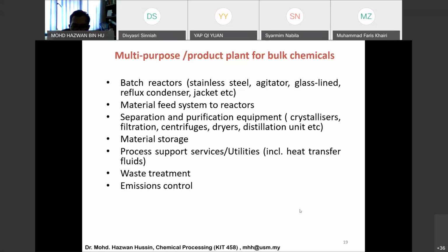So in industry, for your information, if you want to do heating, we are not going to use a Bunsen burner. We are not going to use a heating mantle, because the temperature required in a process can sometimes be too extreme. Then these two things, like a burner, will not be useful. And of course, it is expensive if you use electricity for the heating mantle, or if you use a burner, it's dangerous because you have an open flame. But in industry normally they use steam.